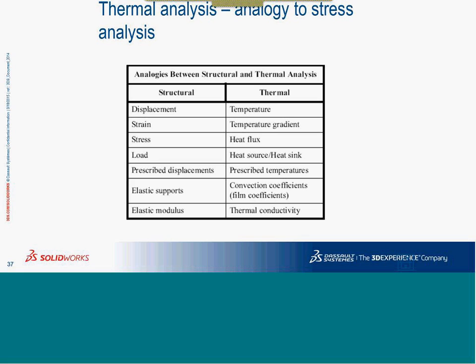The loads in thermal would be more of a heat source in the form of power, or a heat sink, which removes heat from a system. We have prescribed displacements and prescribed temperatures. With displacements, we either push or pull the part in a certain direction. Temperatures instead do a similar thing in thermal analysis.